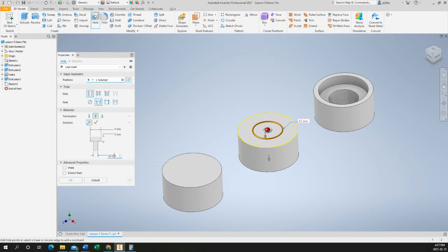So in this case, I will put a value for the bore of the hole, or the diameter of the hole, and we'll use 15 millimeters. For the diameter of the counterbore, we can put in 20 millimeters. And you see how those values were in red until I changed the counterbore? I'll put it back how it was and say maybe a small value like 5. You see that they're both red because there's a disagreement, right?